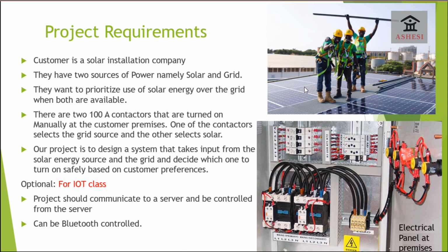The first one is the grid power. The second one is the solar power. And my goal is to be able to prioritize the solar over the grid whenever both solar and the grid are available. So I have been tasked to build a controller for these contactors and then turn on the contactors as per the preferences of my customer.